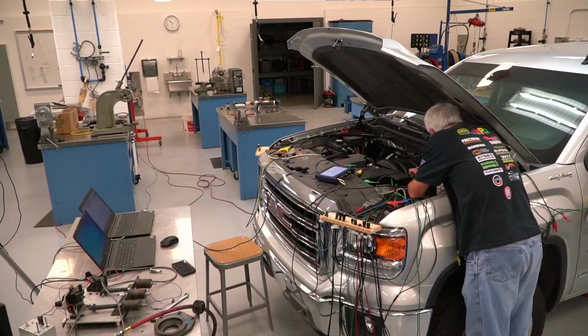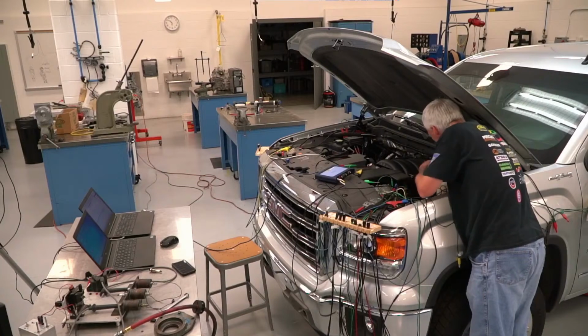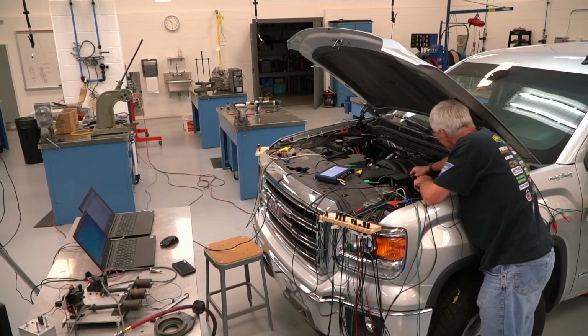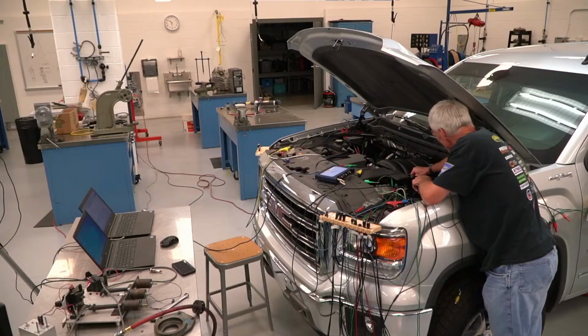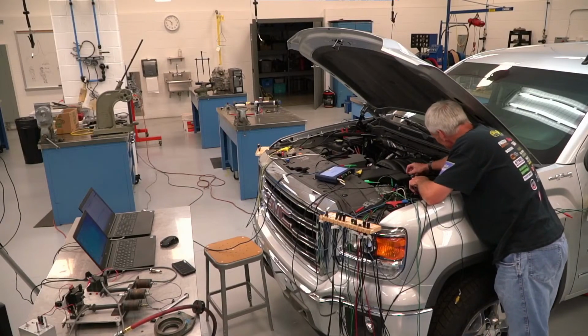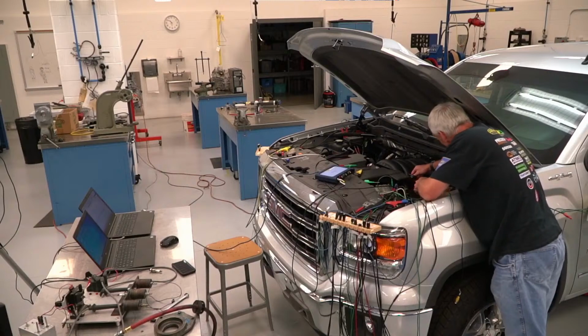These are coil-over-plug, as I mentioned before, and they have 4 wires going to them. If I had a coil that only had 2 wires going to it, it would basically be just the primary windings, and I would have voltage going to it, and the computer would be dropping the voltage in the circuit and turning it on and off.